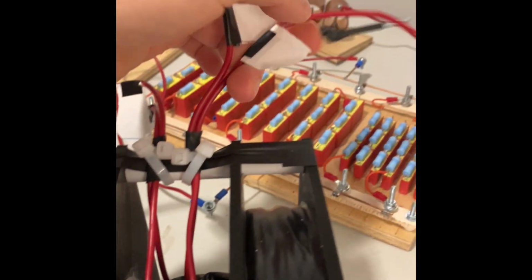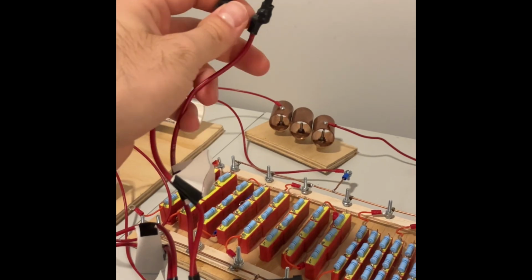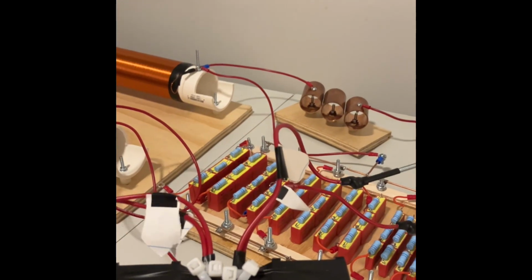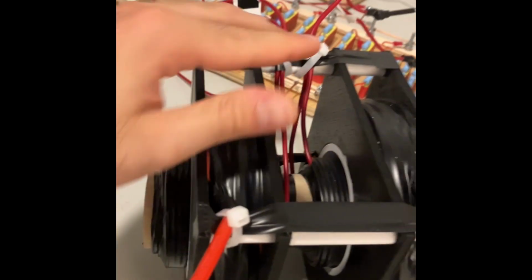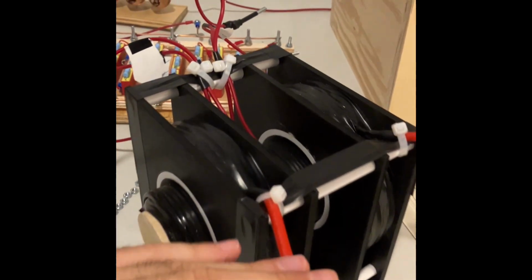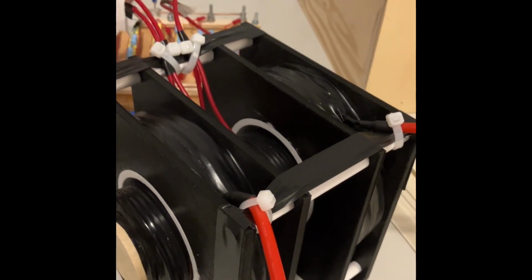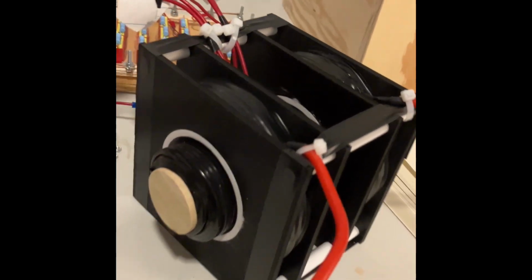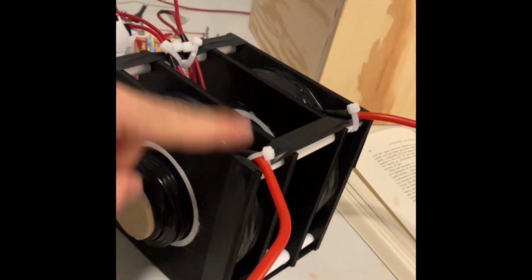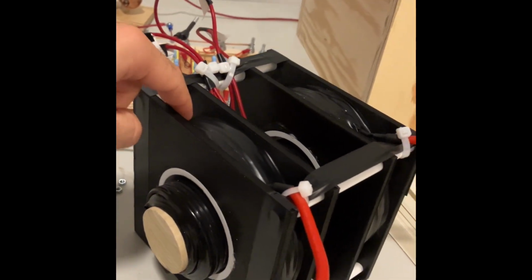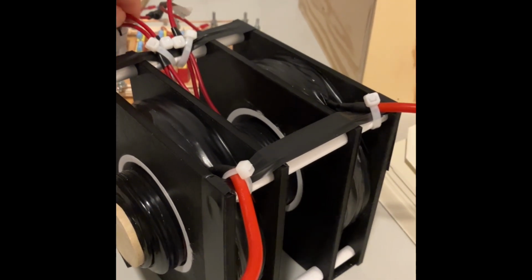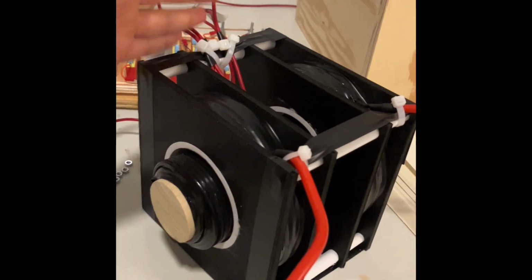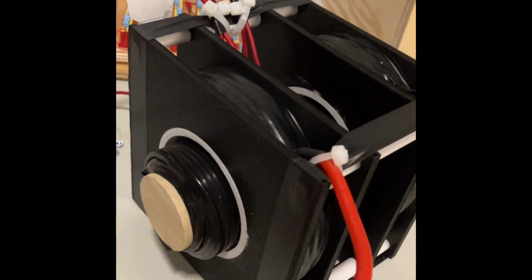So like I said before, we can configure the primary in a couple of different configurations. Leaving all 4 connections free will allow us to do this later on. I'm also trying to keep the high voltage outputs separate from these primary connections coming in. So you can see they're actually on opposite sides of each other. If I were to bring the high voltage parts out of here, we would be at risk of arcing over to these primary connections. So I tried to isolate those as much as I possibly could.